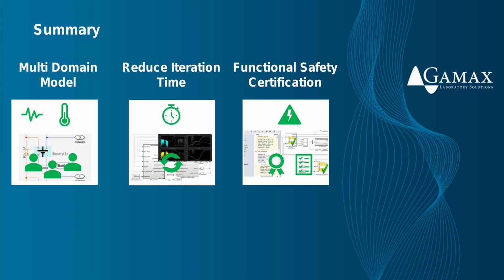In summary, we saw how we can use Simulink as a common design platform for different domains that can be used by engineers in our team from different fields of engineering, which also helps us reduce the iteration time of the design. We can create large system-level models of BMS algorithms for designing and testing purposes that still use the Simulink platform. And the built-in tools aid us in obtaining a functional safety certification for our battery management system before implementing it in a real-world application.